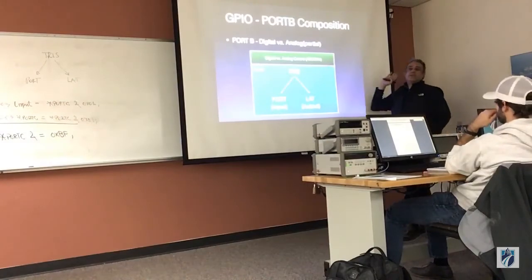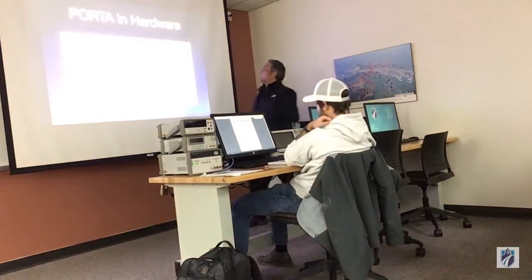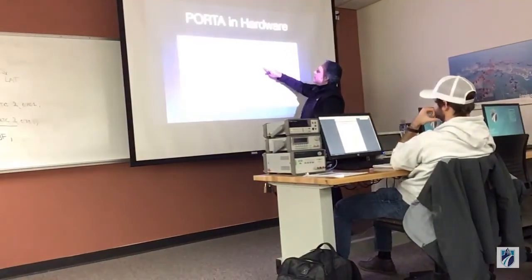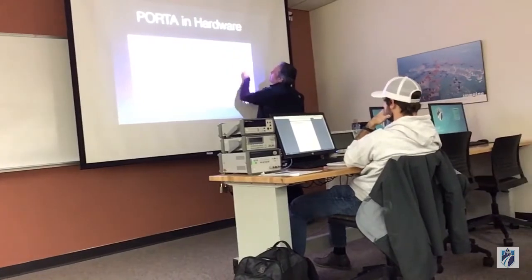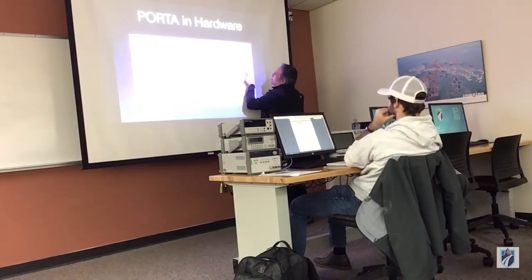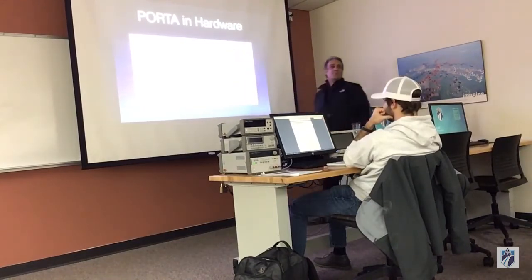Okay? Port B, same thing. Port B contains a whole bunch of analog stuff. Let me show you. Here's port B. Port B is on the top pins from 33 to 40. Here are the Bs. They're all together. But look at the As. Some of them have analog in it. So analog 8, 9, 10, 11, and 12 are located inside of port B.